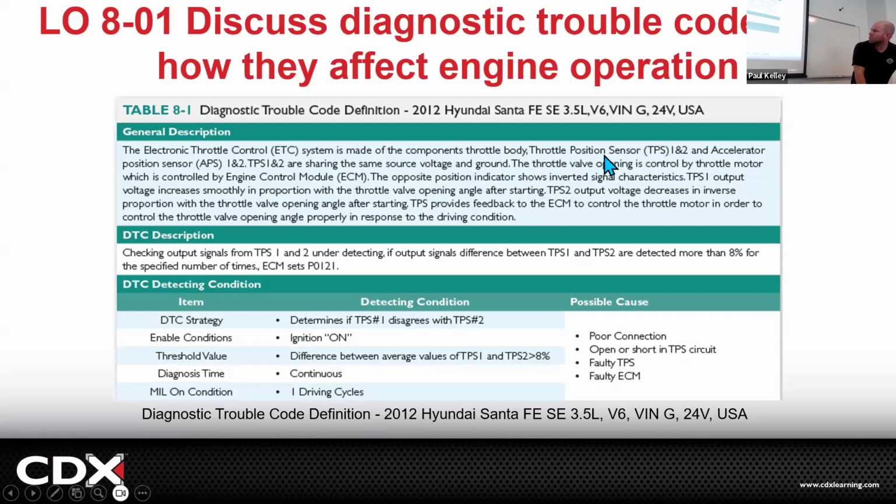And you also notice that it said it has TPS 1 and 2. Okay, that's interesting. So when your throttle opens, it's going to have a sensor to verify your throttle opening is where it's supposed to be. And then it's going to add another one for safety. So your accelerator position sensor has to agree. And if it says 50, it sends a signal to the ECM, and the ECM's like, yeah, 50, and they agree we're good. Make the actual throttle open 50, and then verify it's at 50. And then verify it's at 50 with a secondary sensor. That's TPS1 and TPS2, throttle position sensor, right? So it's a double redundancy. Everything has to agree.